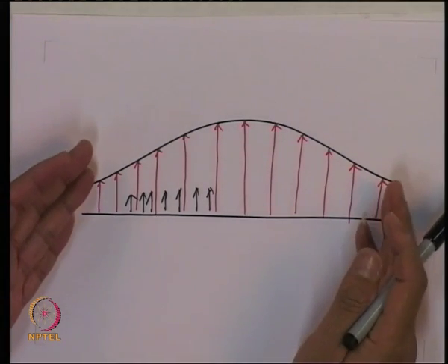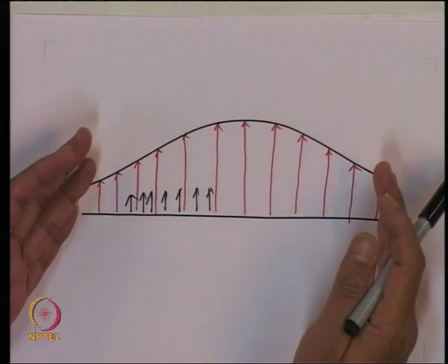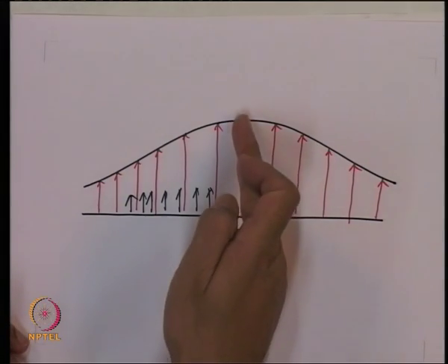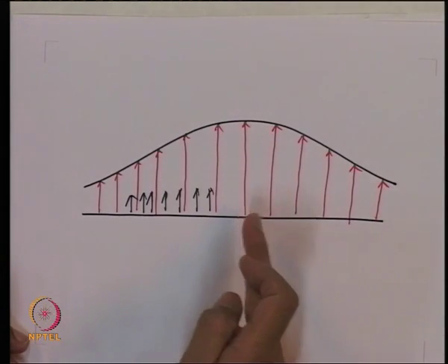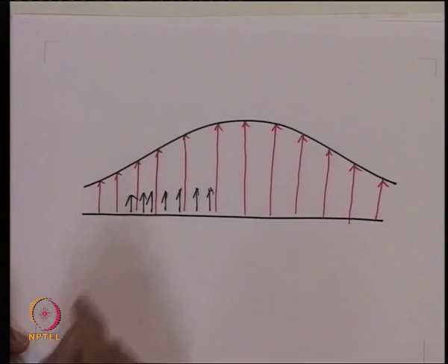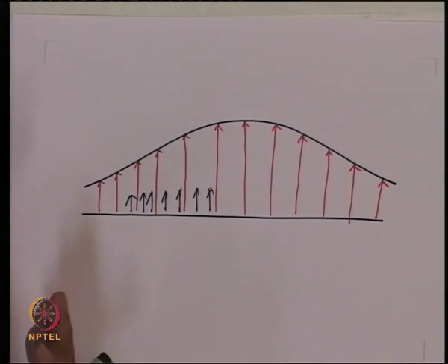However, since we have a spectral width which is large, typically of the order of a few hundred gigahertz, the pulse which rides on this carrier would travel with a different velocity than the pulse which rides on this carrier, because even if we take the material intrinsically, the refractive index is a function of wavelength.